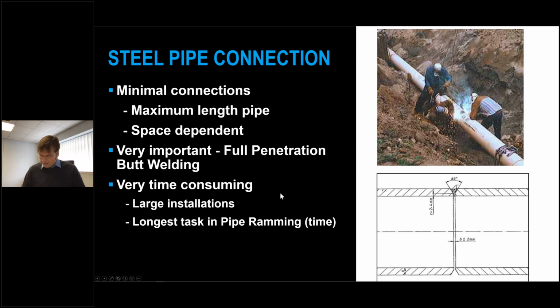It is good practice to have the minimal amount of connections to be done on site, but that obviously depends very much on the space that you have at your disposal. What is absolutely critical is the quality of the butt welding. It needs to be a full penetration butt welding to ensure a successful ram. This can be very time consuming. So again, maximize the pipe length if possible.